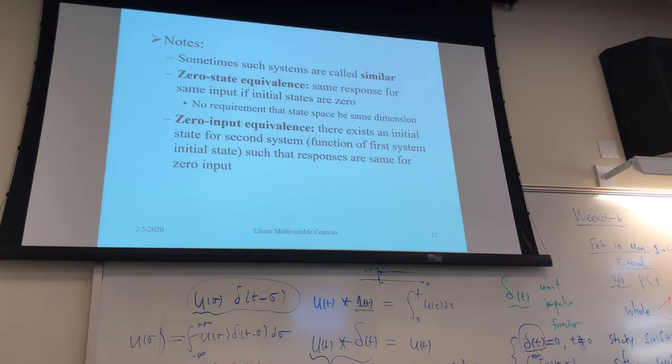And there's another one, it's called zero input equivalence. Initial states, the responses are the same for the zero input. Meaning if you have initial states that are the same, then your response due to the initial states will be the same. So, zero input equivalence. And there's no requirement that the state space be the same dimension.